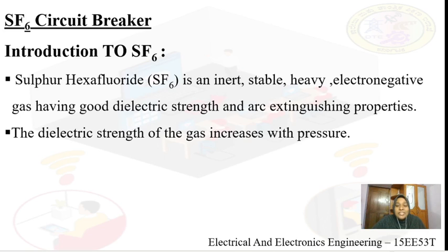Heavy means its density is more. Electronegative. Once the sulfur hexafluoride gas attracts the mobile electrons colliding on the molecule, it absorbs those electrons and becomes ions. These ions will not conduct your current.